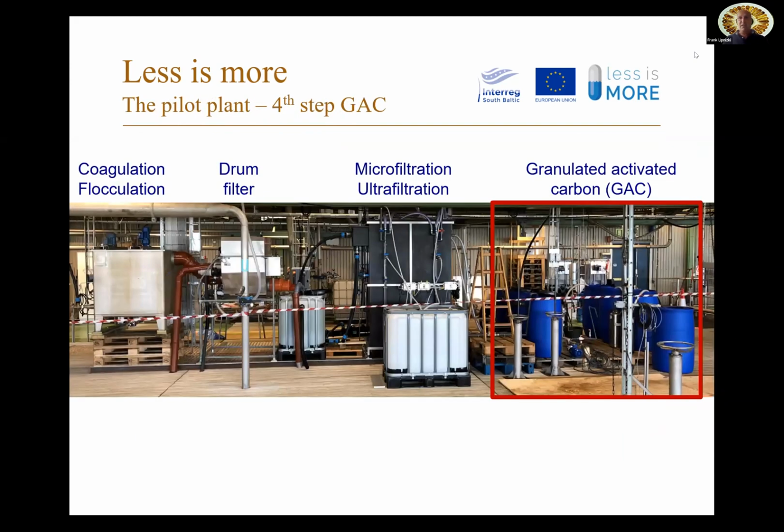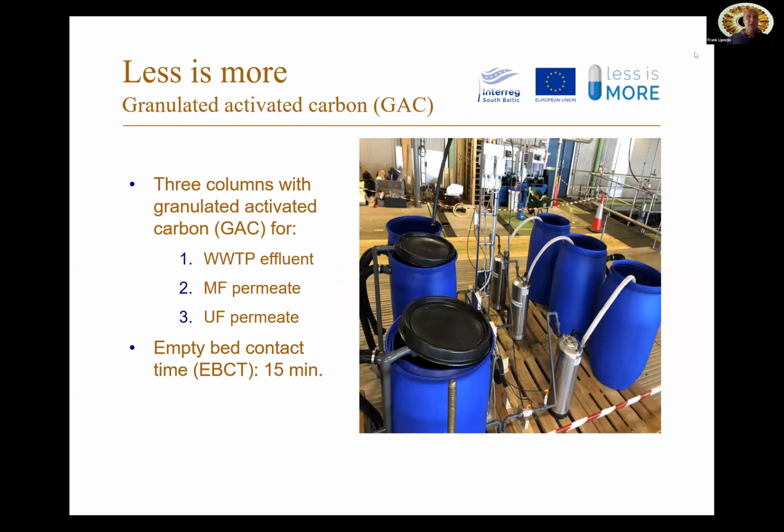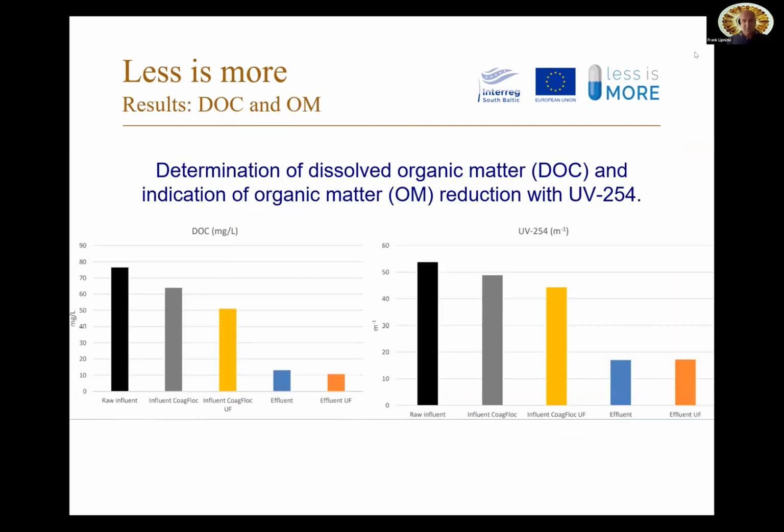And then last but not least, we had granulated activated carbon as a final polishing step. And we had 3 columns of granulated activated carbon for testing the wastewater treatment plant effluent directly, so the original effluent, which came after the processing of the water out there, the microfiltration permeate, and the ultrafiltration permeate. And the empty bed contact time in all 3 cases was 15 minutes.